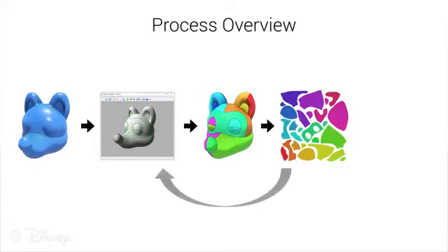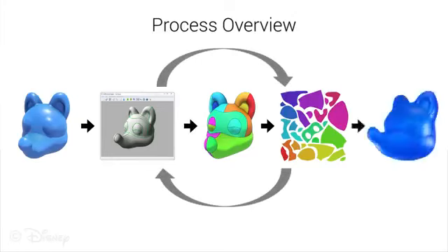Our system is fast enough to allow interactive exploration of seam layouts. The designs produced by our system are feasible and can be used to fabricate inflatable structures. In the following, we will demonstrate the design process in more detail.